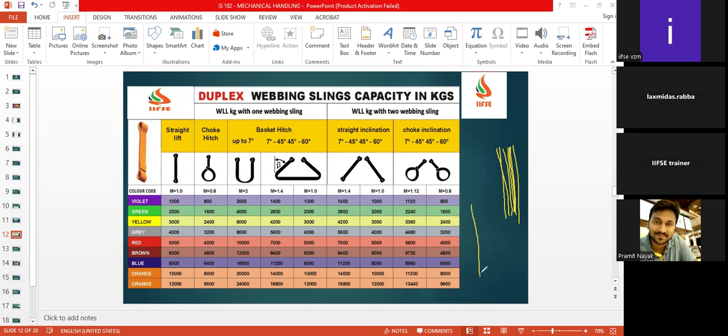And another way of looking at the capacity of the belt is, this is how this belt looks. Sorry, I have not drawn properly. Here you will have an eye, and in between the eye you will have a tag. In this tag also, they will give the capacity of the belt. Due to usage, these tags get worn out very easily while applying these choker methods. So it is always good to have an external tag on this eye area so that we can understand when these belts have been calibrated.